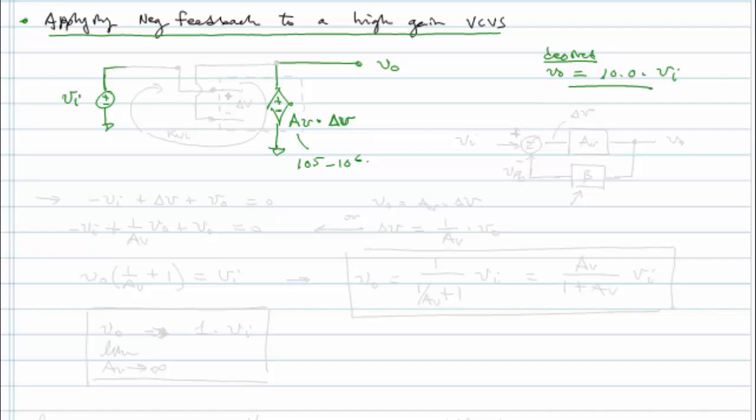So let me draw something here. We'll put our input voltage delta V like such. So this is, if you will, I will kind of draw a box around this voltage controlled voltage source. Okay, and these are the terminals that are the controlling voltage terminals. And how do I want to wire them up? Well, I want to feed VI into this amplifier path.